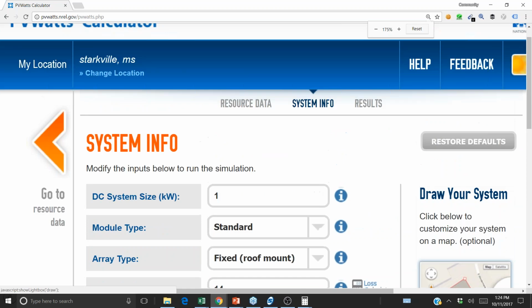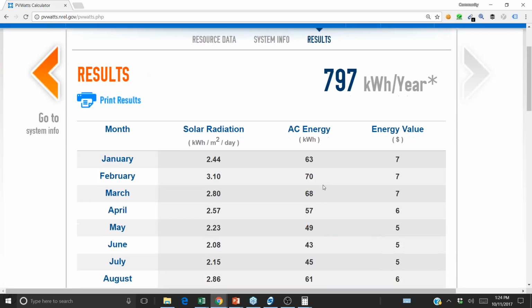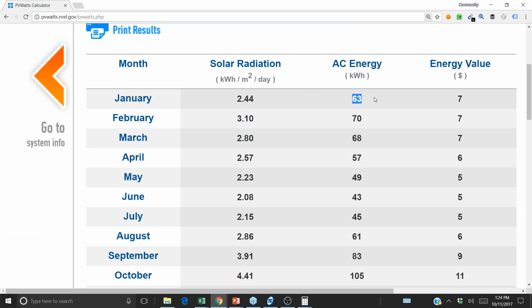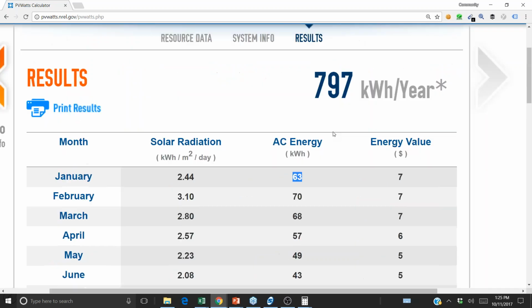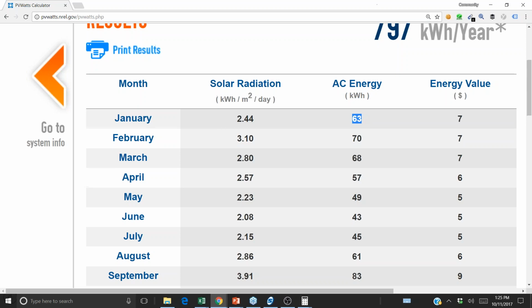And what I can see here is that now, well, in Mississippi, it still didn't make that much of an impact. So I might as well just go with the shallow roof tilt anyway. But if you go into northern climates like the north part of the United States, or up into Canada, you might find that mounting not the entire array, but a couple of circuits down the side of the building and off grid to boost your wintertime production, if that indeed is the priority.